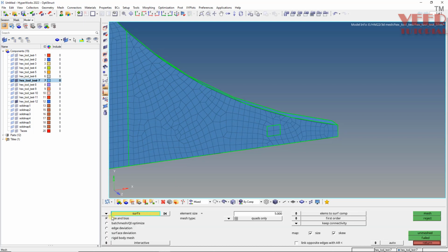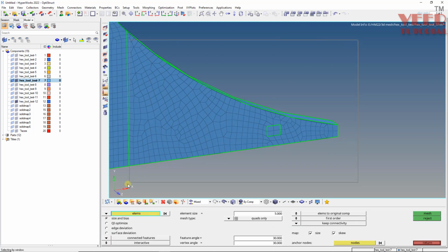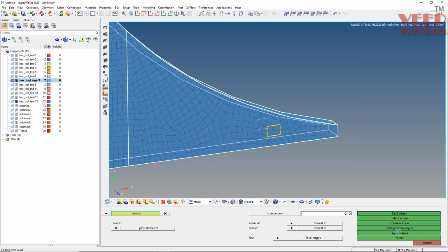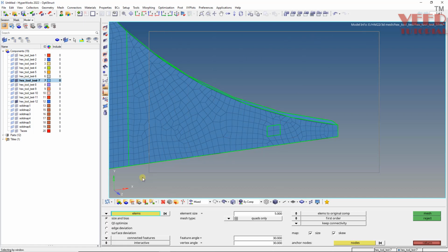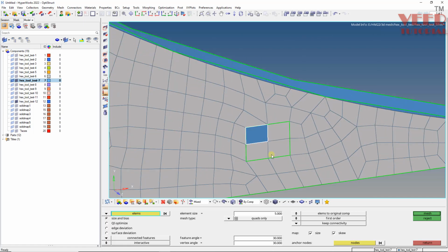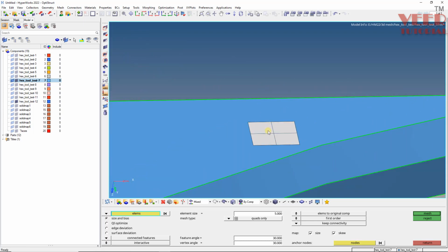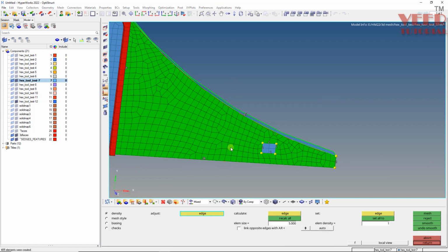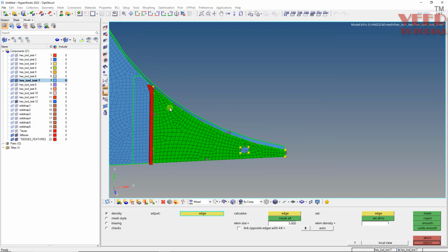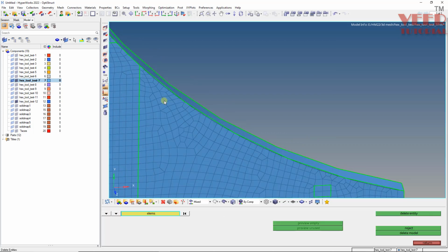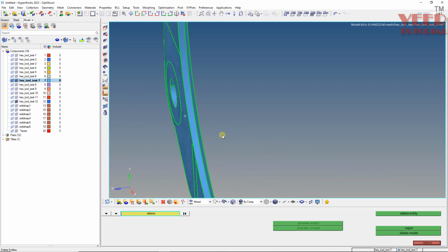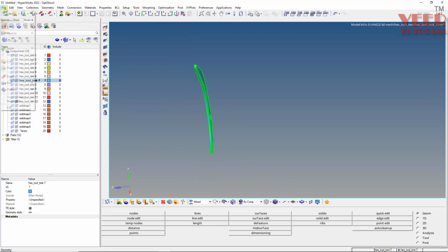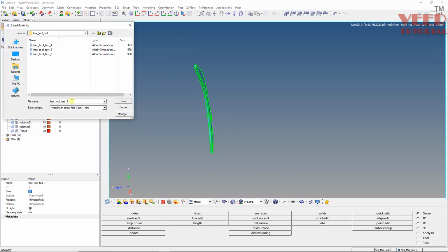So I will remesh this once again. To remesh this, select this complete. Before this I will preview equivalence this. Equivalence, then remesh it. Pick up everything, then leave this element. And other elements are selected, we don't need this. Okay. Now remesh it. Like this. So in this way we have completed the meshing of this face. Now we have to drag this on the right side, and we will do this in the next lecture. And I will save this file, save as, this is number 4.